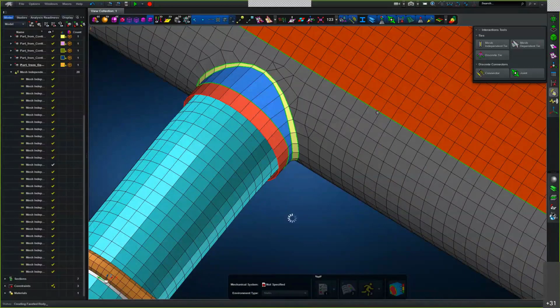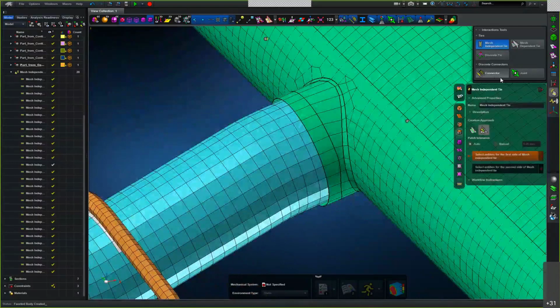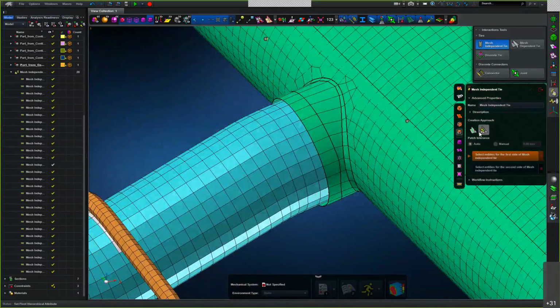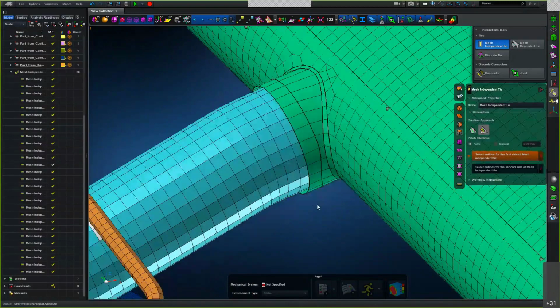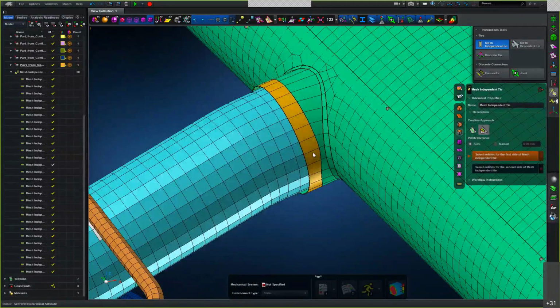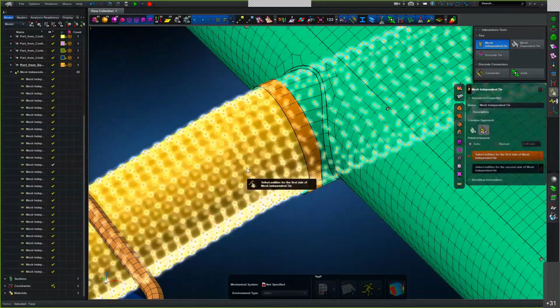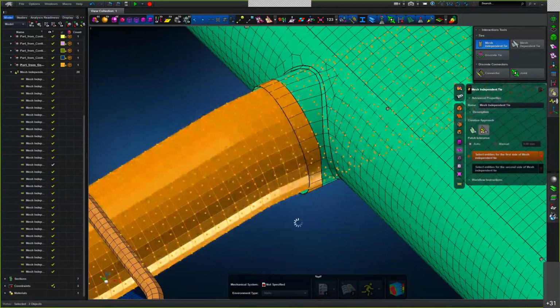That's a good warning you have about making sure you preserve all of those changes. I frequently forget. Yep. So now I'm going to go back in here and I'm going to manually create my glue. I actually have geometry here, so I can just pick those faces. Okay, pick the right filter. I can just pick this face on one side, and then I can pick, yes, this mesh body on the other side. Go ahead and create my glue.